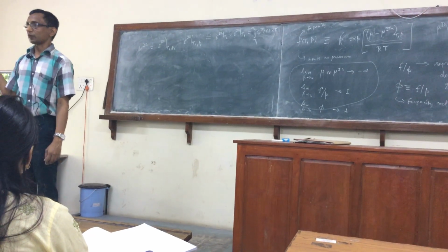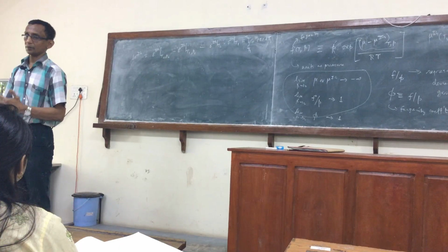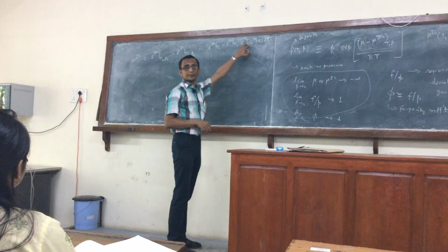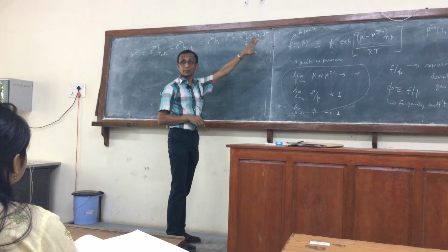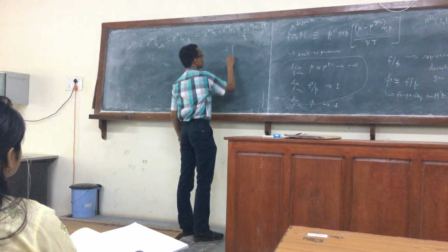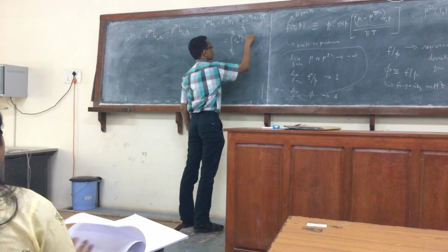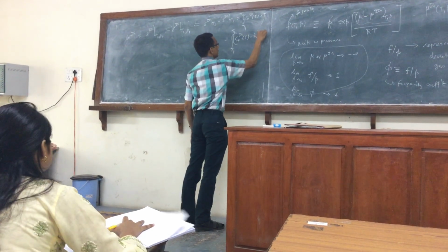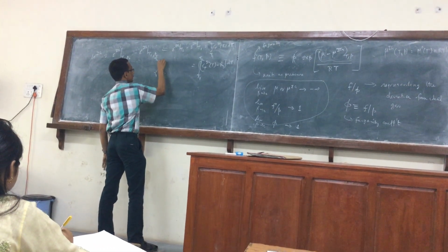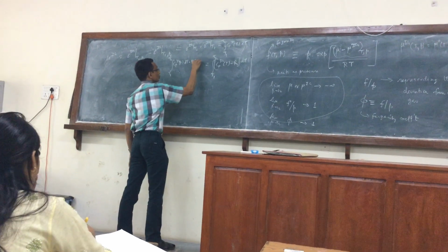Or if you take the view, since tables actually give the Cp of the ideal gas, right? So if we want to now express everything in terms of Cp, then we know that for the ideal gas, Cp minus Cv is a constant and equal to R. This is per mole specific heat that you have to keep in mind. So this can be written as the integral from T1 to T2 of CpIG, which of course will be a function of temperature, minus R dT. This can then be written as the integral from T1 to T2 of Cp dT minus R times (T2 minus T1).